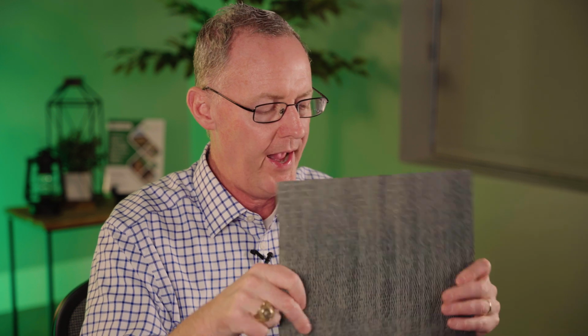But what happens is when you put the adhesive in here, this becomes extremely strong. The way we test it, though, is we make basically coupons. And so we'll take a panel like this. We cut a dog bone out, and then we basically pull on it.